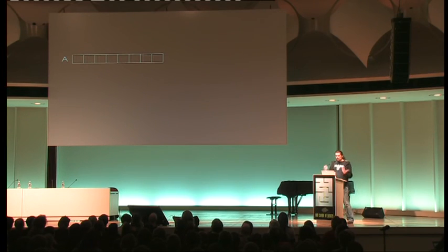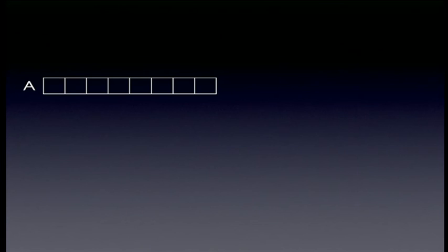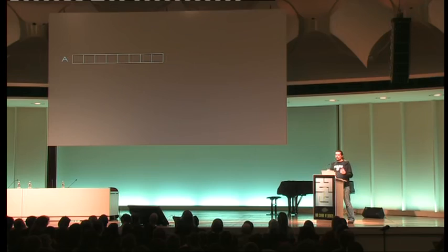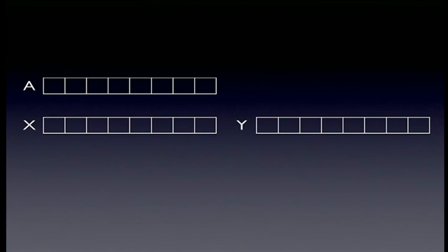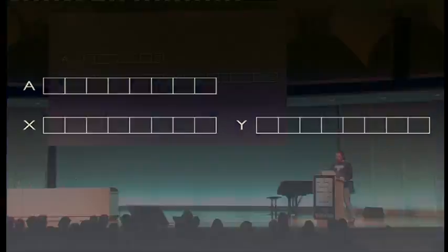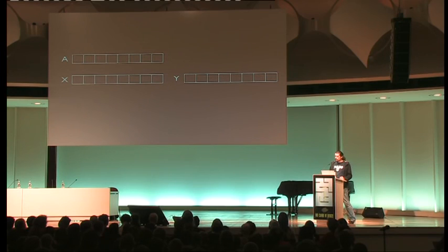So from a more theoretical point of view, what's the programming model? You have the A register, the accumulator. It stores everything and it transfers everything. Whenever you handle data, whenever you do arithmetic and logic, it goes through your single A register. And the index registers, which aren't as powerful, they can count up and down and be used as an index in accessing an array, but you cannot do any arithmetic or logic on them.